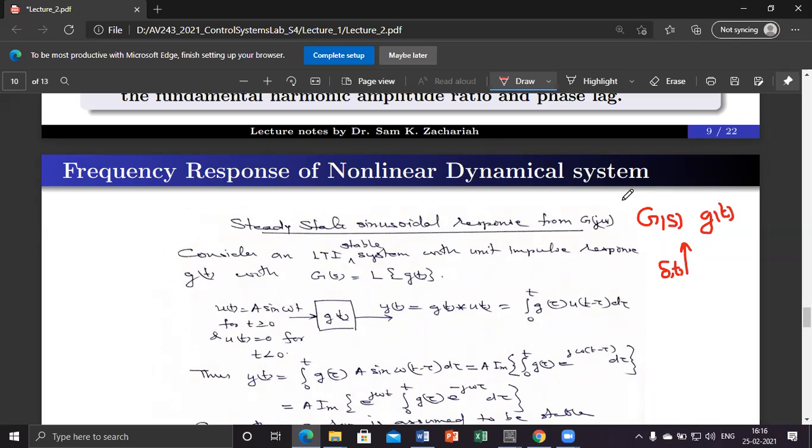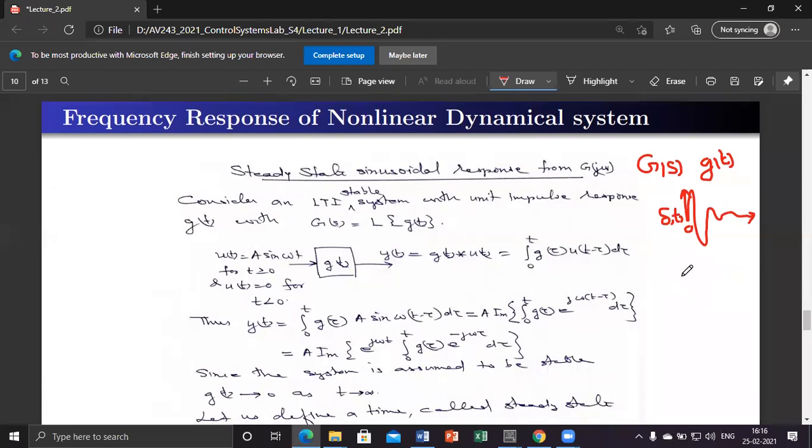And if all the poles of G(s) are in the left half of S plane, if you give a delta(t) command at 0, the response, initially there will be some transients. Finally, this transient will settle down towards 0, so that the limit of g(t) as t tends to infinity will be 0. That you have studied, I hope.